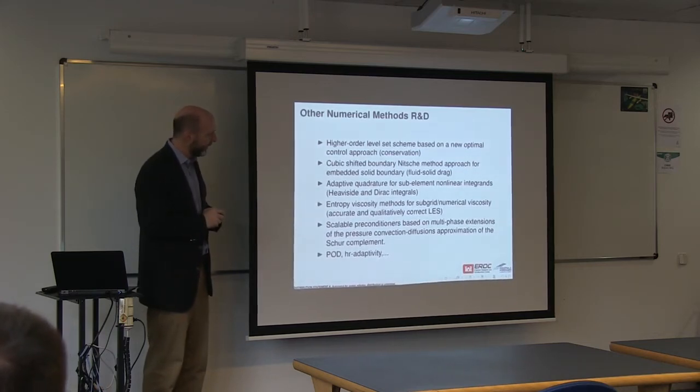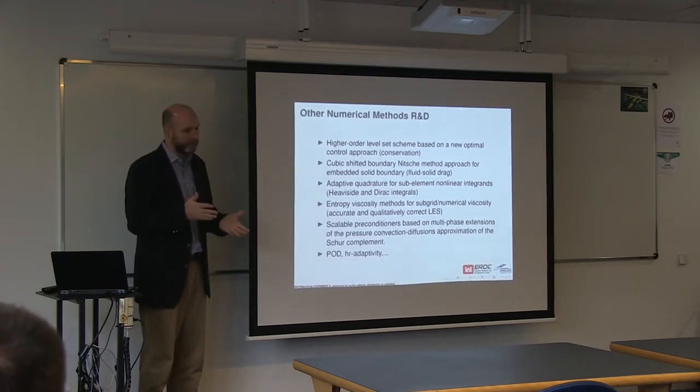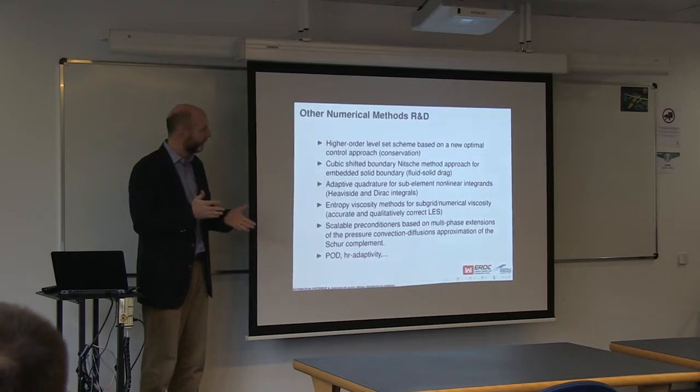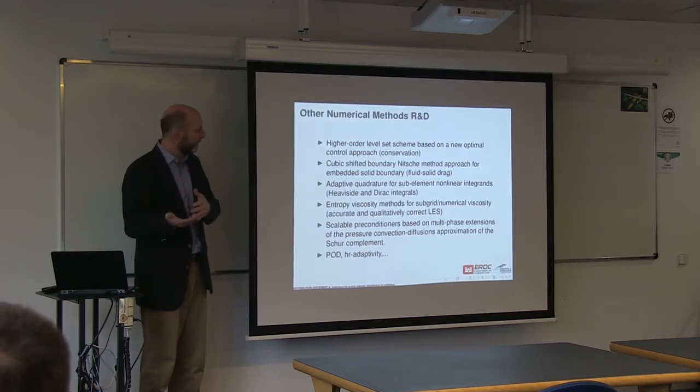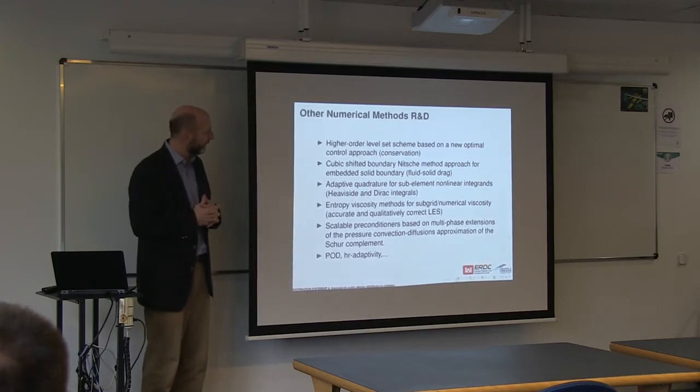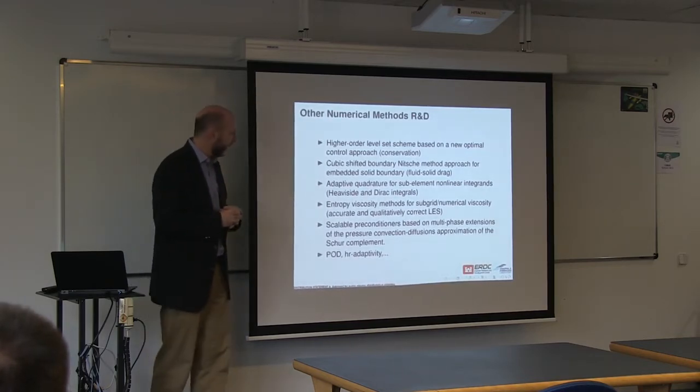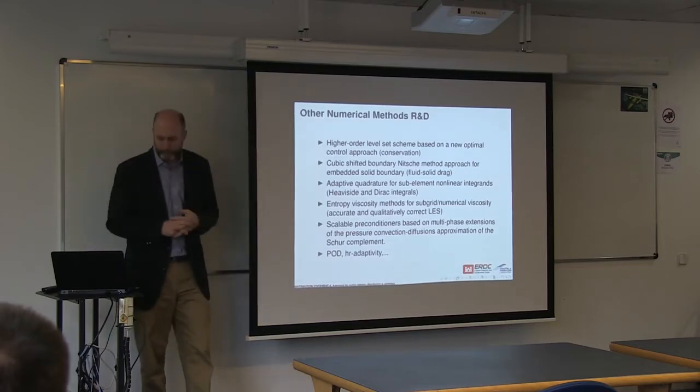We've also been in the process of shifting our stabilization schemes for the Navier-Stokes equations from variational multi-scale methods or SUPG methods to entropy viscosity type stabilization schemes. And we're also working on scalable preconditioning.